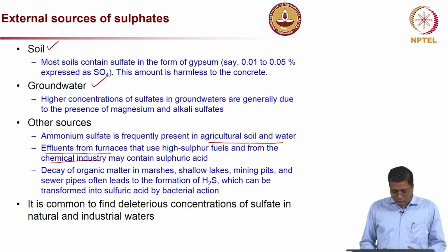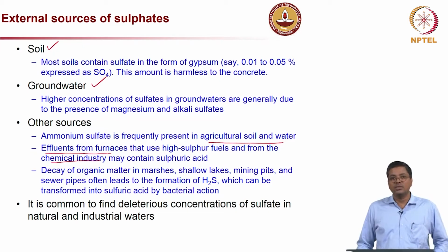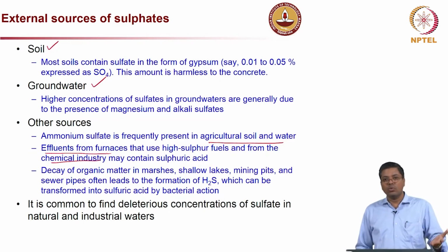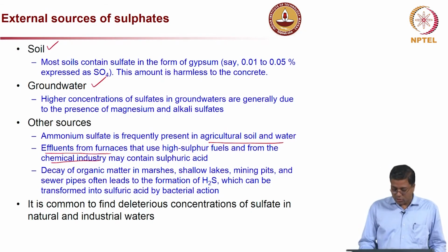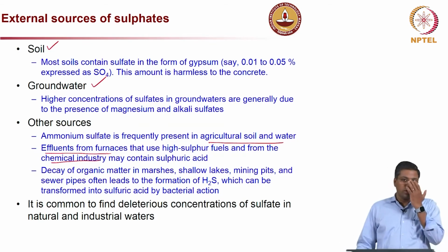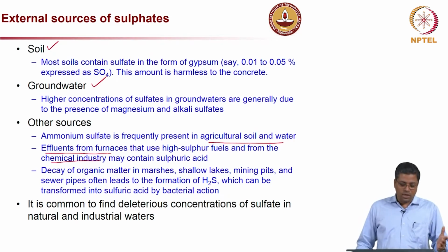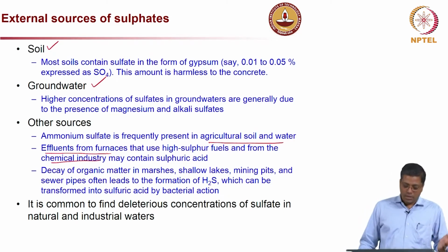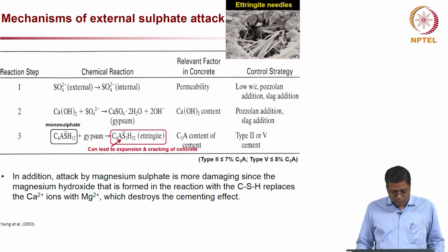Now, the bottom line of this slide is that it is not that difficult to find high concentrations of sulphates in either soil or water bodies which are in contact with concrete structures. So, you have to really think about this and make sure that the type of concrete which you are using is sufficiently resistant against sulphate attack for the desired life which we are talking about.